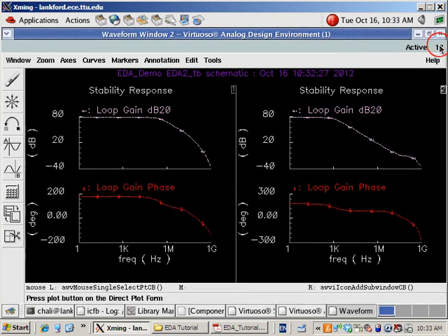And if we compare them, that's obvious. See, the phase starts to drop earlier. Does that make sense? The phase starts to drop in the original case at this location, which is around, let's see, 50 kilohertz. And now on the right hand side, the phase starts to drop around 470 hertz. So the dominant pole frequency has been reduced.